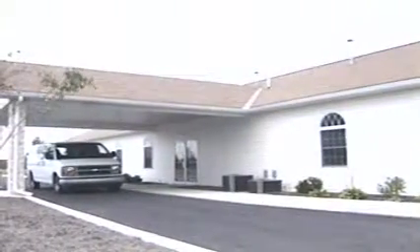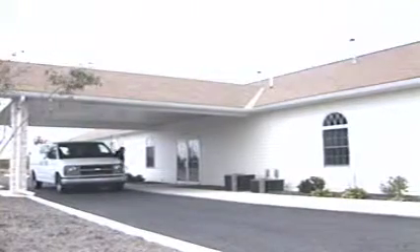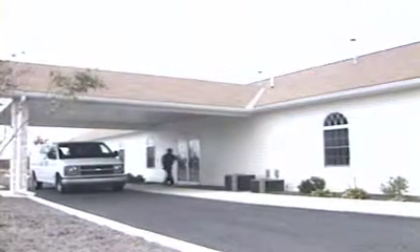You arrive at the church office knowing only that the air conditioning unit is not cooling. So start by asking questions. It was nice in here yesterday, but when I came in this morning, it was really hot and humid. Where's your thermostat located? It's in the next room here, and it takes care of 2 rooms and the office. What is your setting on the thermostat? That's a 55. That seems to be an awful low setting.